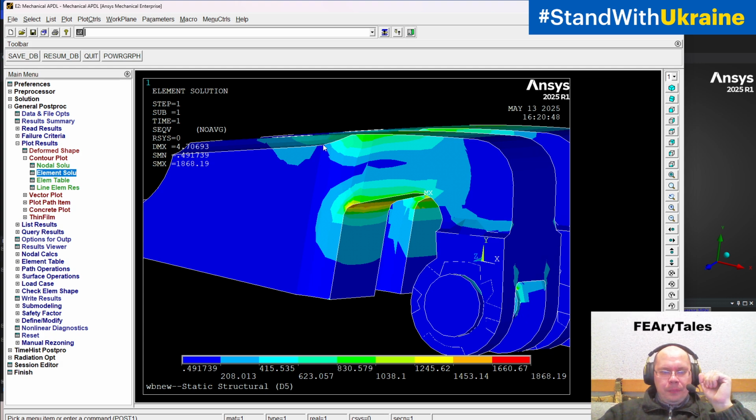Many years ago, we needed to start Ansys with this option, Power Graphics On or Power Graphics Off. And during the whole work, we work with one type of these graphics, either with full representation, like at this moment, or with simplified. Today we can simply change it by the button or by commands on the fly.